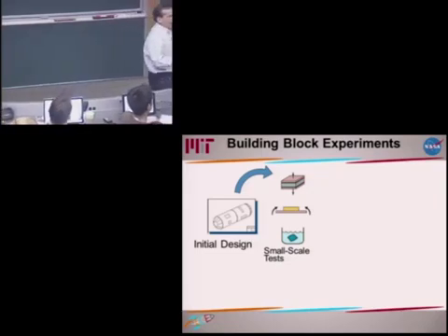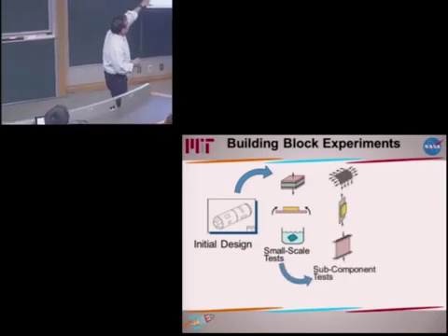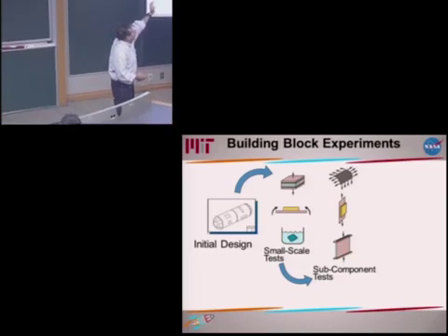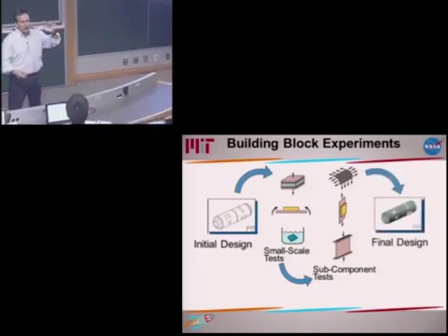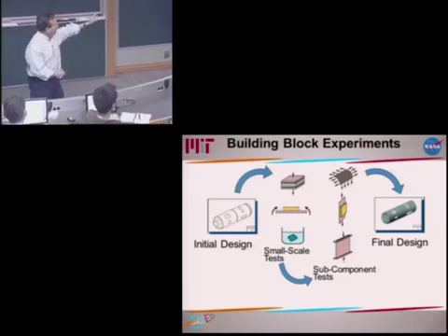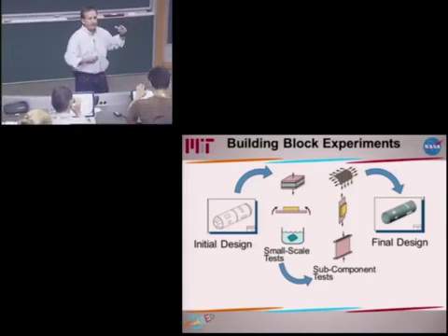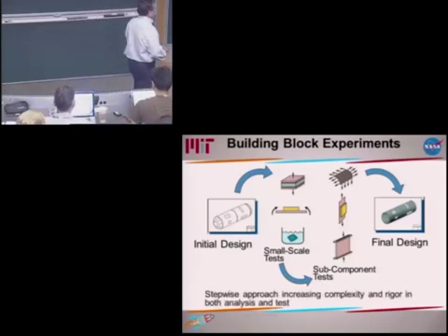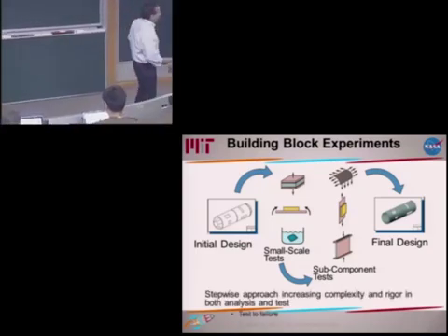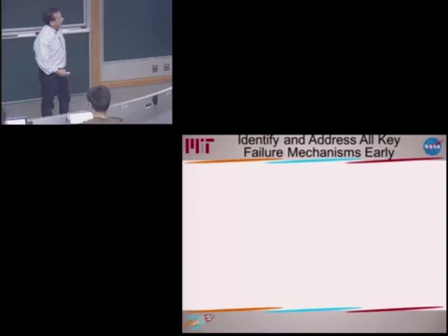So you have to maintain that vacuum. And it's very easy. You could do these tests at a very small scale in a laboratory. But in a building block approach, once you pass those tests, you continue more and more rigorous in your analyses, more and more constraints till you finally test a full-scale specimen. And you take the stepwise approach, increasing rigor in the analysis and experiment, and you're constantly testing to failure so you know the limits, you know if you can predict it.